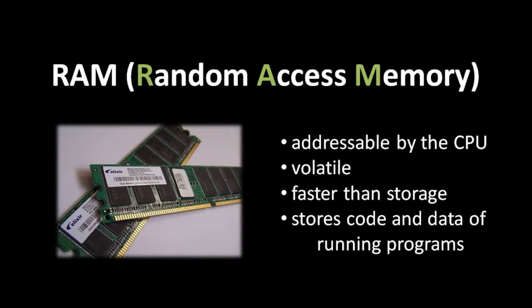A notable characteristic of RAM is that it's volatile, meaning that as soon as a RAM chip loses its steady stream of power, the content of the RAM gets scrambled. None of the bits can be relied upon anymore because, without power, they get flipped unpredictably. What this means in practice is that when you turn off your computer, the contents of RAM are lost nearly instantly. The next time the computer is turned on, the contents of memory start off in a total jumble, as a bunch of random garbage. So this explains why the operating system must be loaded from disk every time you power on the system. Despite this annoying characteristic of volatility, we use RAM chips for system memory instead of, say, a hard drive because RAM chips are much faster to read and write.